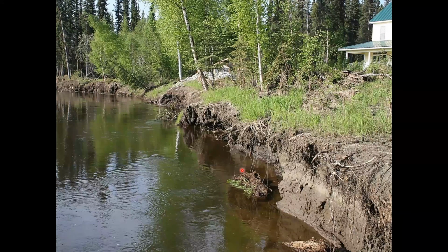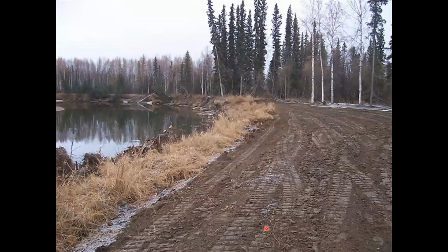These techniques also work on another Chino River site. I like to use this photo because you can see this is very fine silt, and root wads work perfectly in this fine silt. This particular site was having problems, and this is a vertical drop. According to my coworker, it was probably 10 feet straight down from here. But they were able to get in and get some root wads installed.